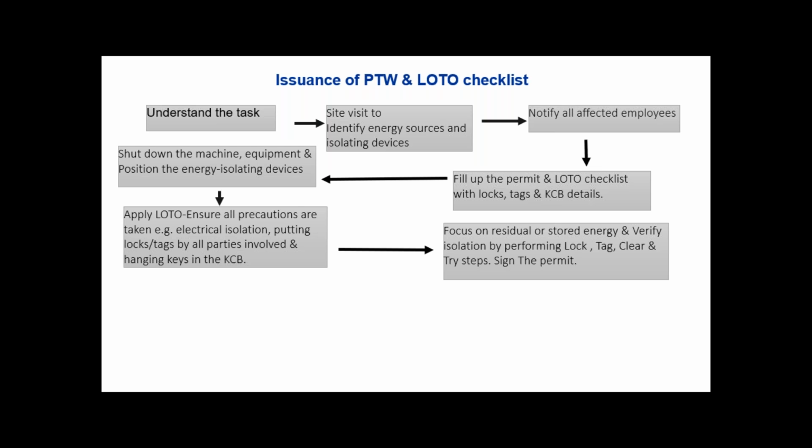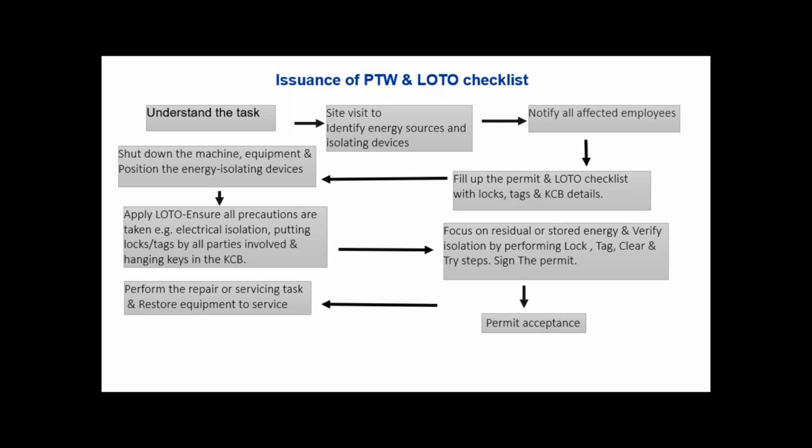So after verification of all these isolations to the energy sources, to the stored energy or to the residual energy, then we can give the green signal for doing the activities. That is nothing but the permit acceptance. Then perform the repair or servicing task and restore the equipment to service.